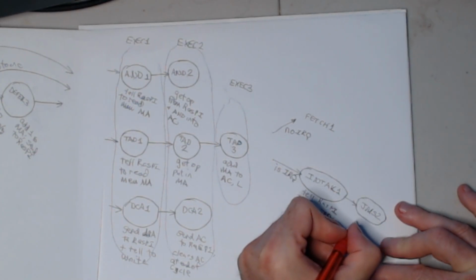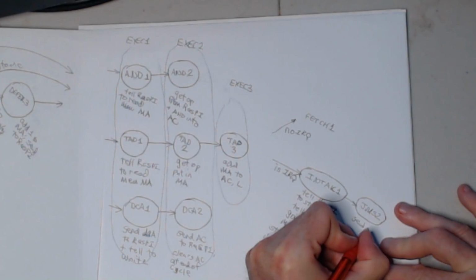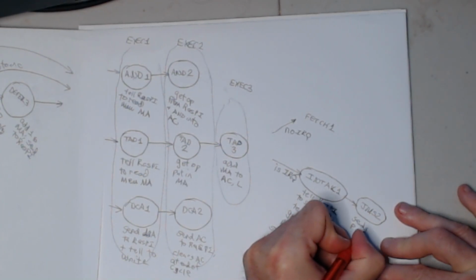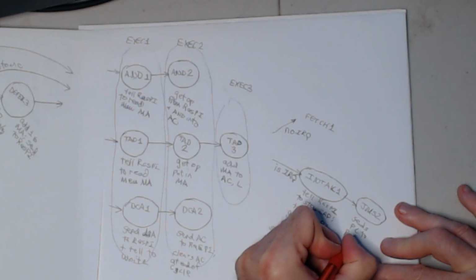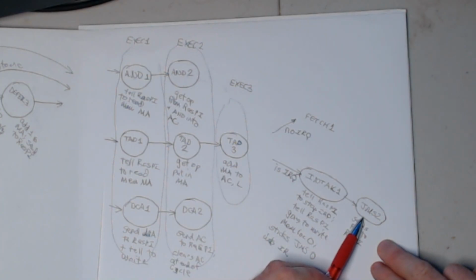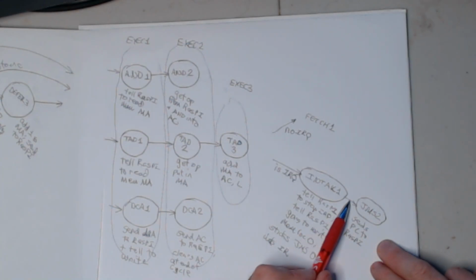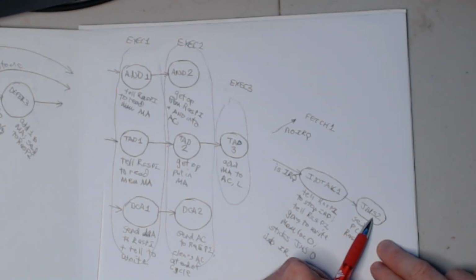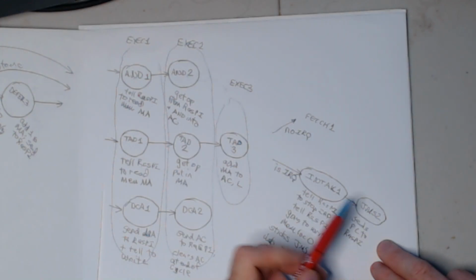which sends the program counter to the Raspberry Pi. Just a regular JMS as if it were a JMS instruction, because we have a JMS 0 instruction in the instruction register. So we can just let it go ahead and do what a JMS instruction would normally do.